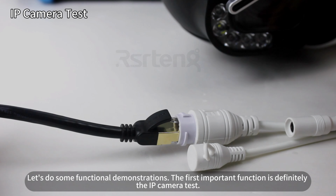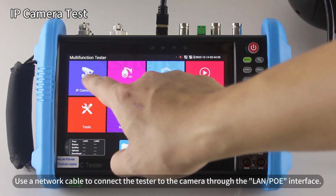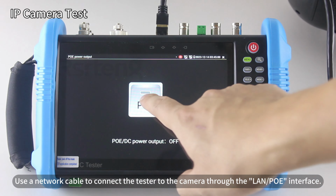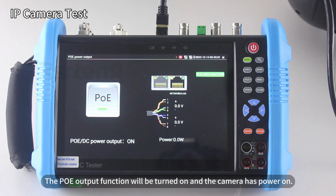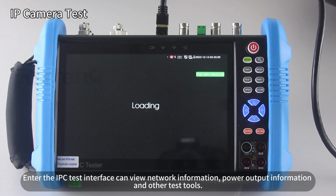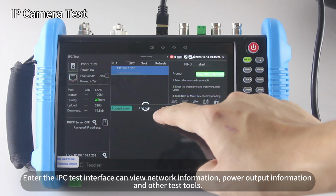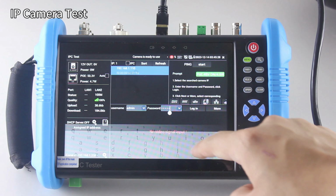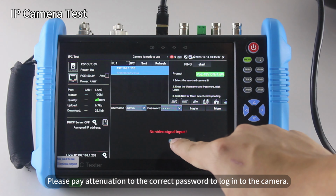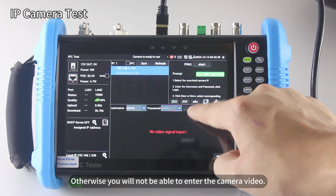The most important function is definitely the IP camera test. Use a network cable to connect the tester to the camera through the LAN by PoE interface. The PoE output function will be turned on and the camera powers on. Enter the IPC test interface, where you can view network information, power output information, and other test tools. Pay attention to the correct password to log into the camera. Otherwise, you will not be able to enter the camera video.